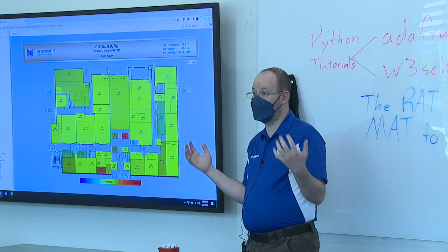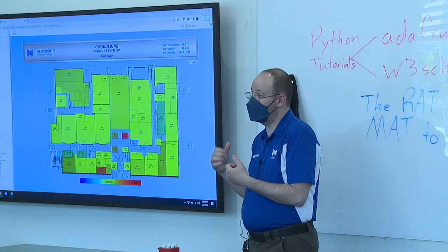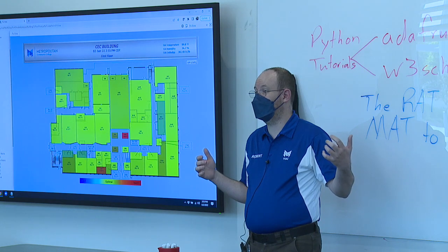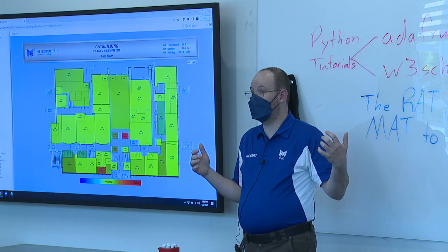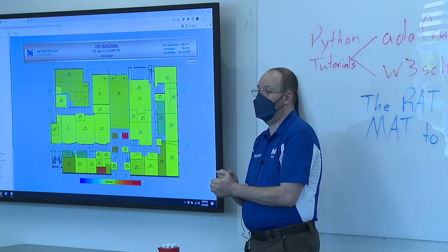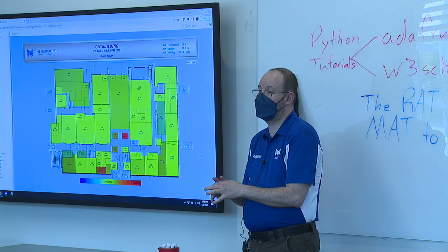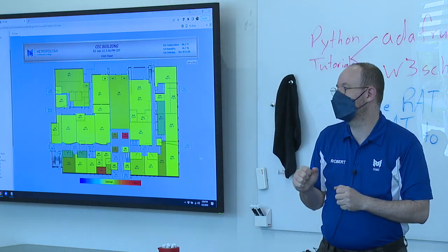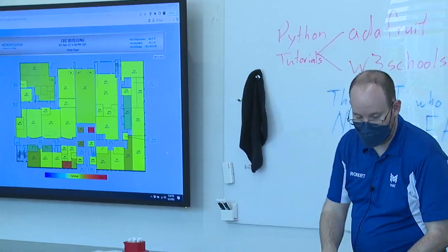There's too much diversity in the system on the air handler side. Our air handlers run at 100% supply fan in the middle of the winter because they just don't put out enough air. And if you can't put out enough air in the middle of the winter, you did something wrong. Personal beef, don't worry about it.